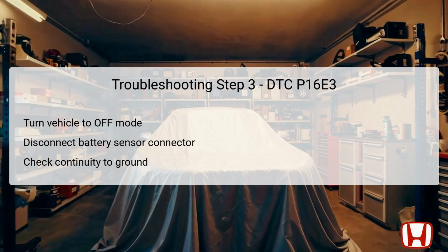The objective here is to confirm that a clear electrical path exists. If continuity is verified, this suggests that the wiring is intact up to that point, prompting further investigation. If continuity does not exist, this points to a potential issue in the wiring, requiring immediate attention to avoid further complications.